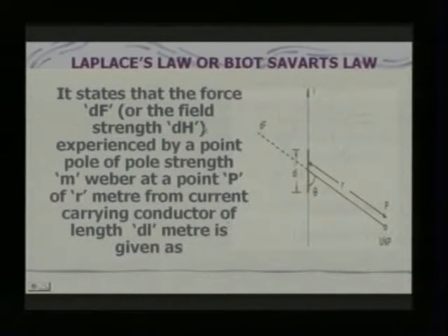Now, we will see the other law, that is Laplace's law or Biot-Savart's law, to find the field strength of a differential length dl at a distance of r meters at a point P. It states that the force dF or the field strength dH experienced by a point pole of pole strength m Weber at a point P of r meter distant from current carrying conductor of length dl meter is given as